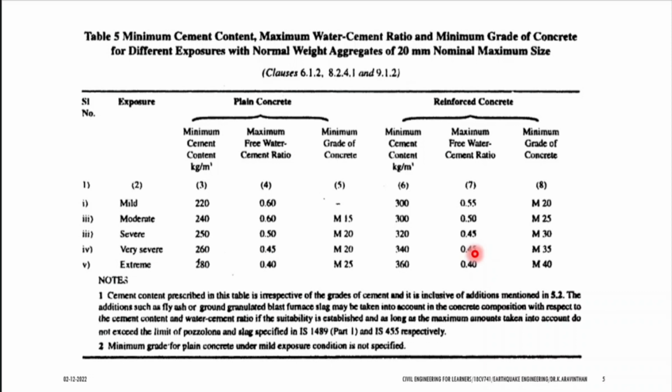having a cylindrical water tank, yes or no? On top of all structures you see a black color cylindrical water tank, which will be 1000 liter or 2000 liter. When you install a 2000 liter water tank, what is the weight acting on a slab? 2000 kg. But the live load you take is what? 150 kg. How many times of increase? 12 to 13 times of increase.